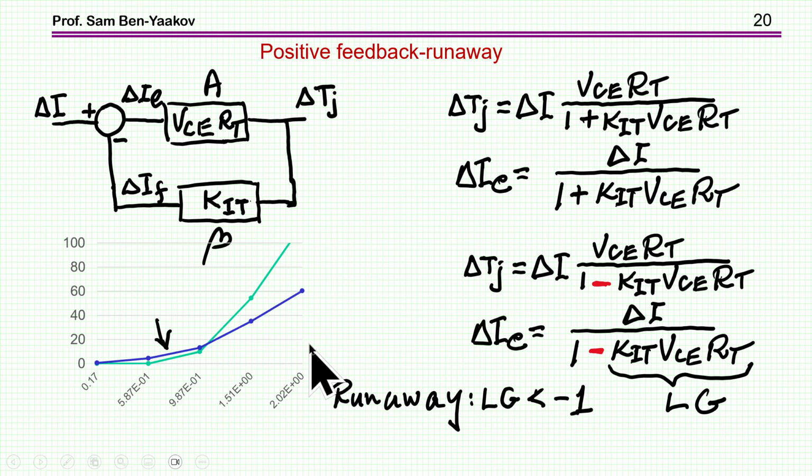Now, in the previous discussion, we assumed that we are in this region both for the IGBT and for the MOSFET, of course, because the MOSFET is only this region here, in which we have a negative temperature coefficient. That is, as the temperature goes up, the current goes down for the same VCE. Now here, it is reversed, okay? So we have to put here a minus. Now obviously we can understand when this comes to be 1, then it explodes and this is the runaway. But if it is smaller than 1, it's still stable. It's not that it's not stable.